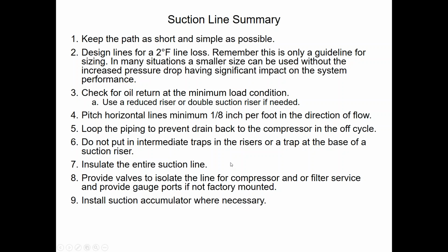Of course, suction lines need to be insulated. Isolation valves for the compressor, those are always nice to have. A lot of times those are already built into the unit. Filter dryers should have isolation valves if they're changeable core style.